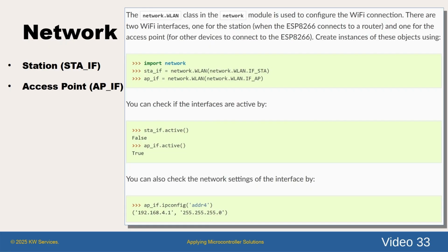The author wanted the station interface so that the code could connect to the NTP time server, and also to update a remote MQTT server. For our program, I kept the NTP connection, but I disabled the MQTT publish function. I wanted to defer MQTT to a future video. If you're interested, though, the code is there in the file, but as comments.